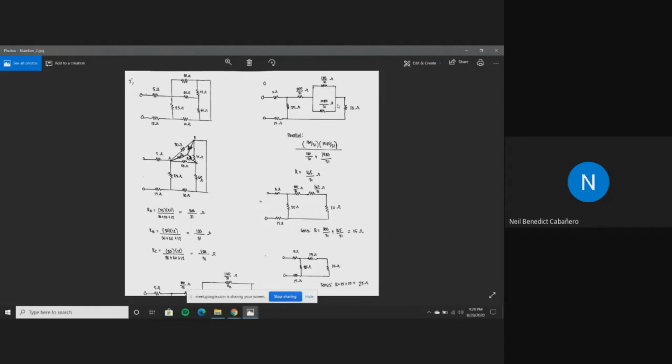So in order to get the total resistance, we use the formula for two resistors, which is R1 times R2 over R1 plus R2. So 180 over 31 times 1980 over 31, all over 180 over 31 plus 1980 over 31, which is equal to 165 over 31 ohms.